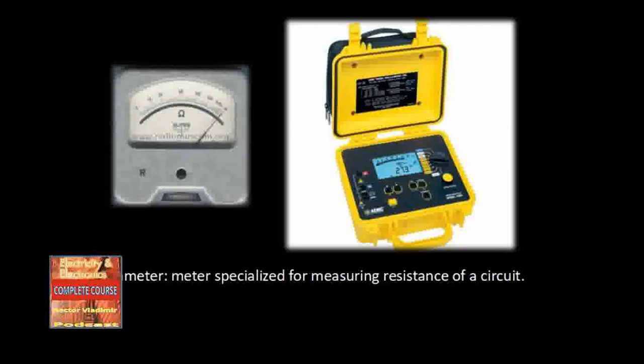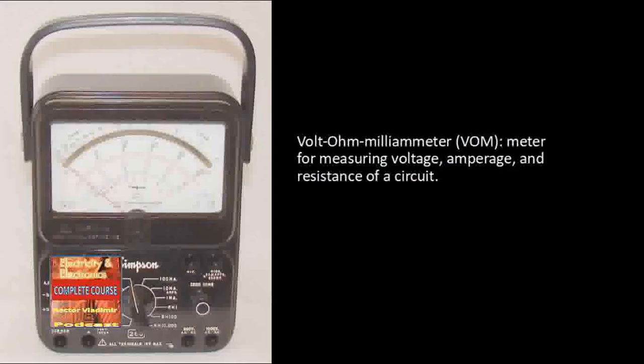When measuring resistance, be certain that no power is applied to the circuit. It is best to disconnect the voltage source before taking any resistance measurements. In general, it is not necessary to observe polarity when taking resistance measurements. However, as you advance through your studies, polarity must be observed when checking certain solid-state devices. Always adjust and zero the meter on proper range before measurements are made. The ohm meter should be readjusted after changing ranges or after prolonged use. An open circuit will have an infinite reading.